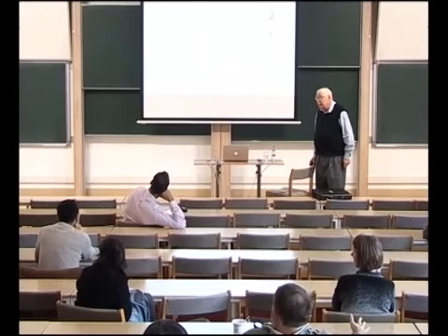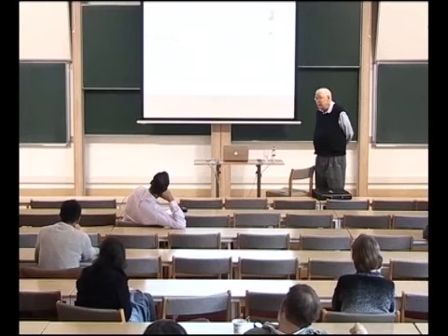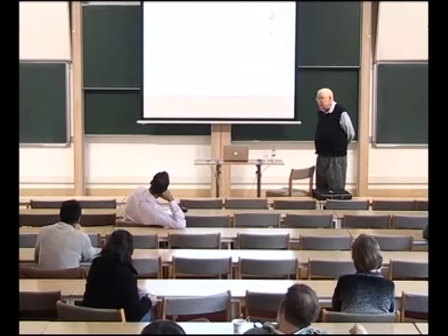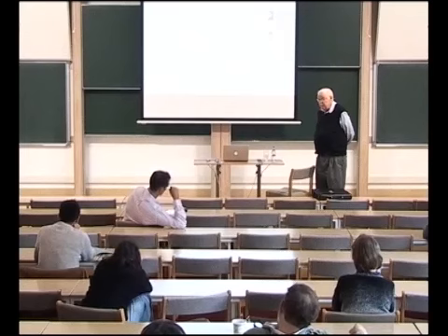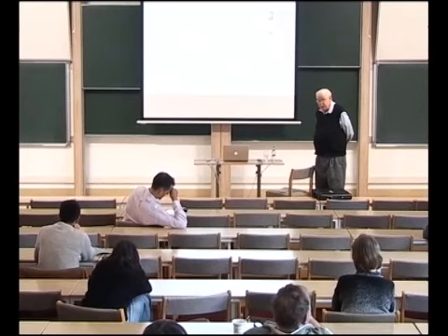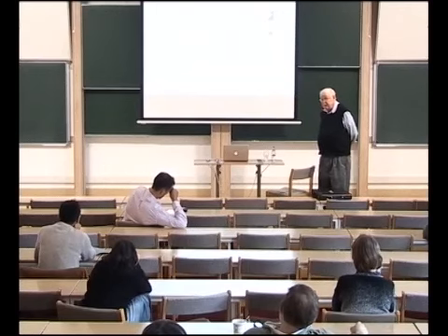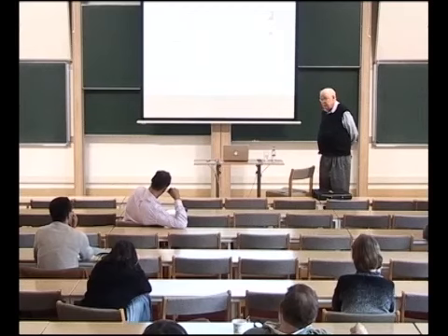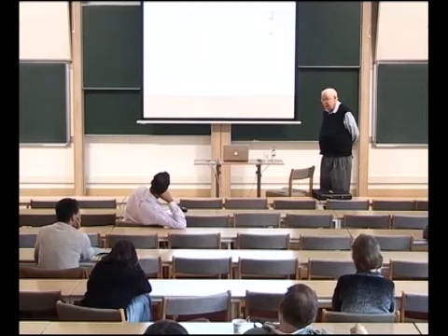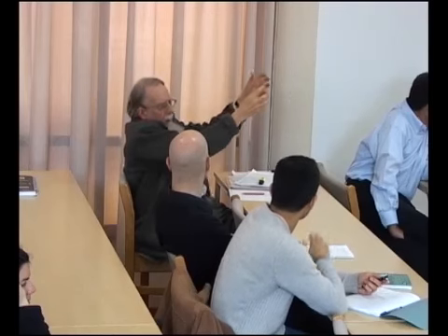Okay, which I take it that means you're using small displacement, so the viscous wake has little chance to develop, because of course those formulae are for inviscid irrotational flow, and in which case the 0.5 and the 1 are perfectly precise. Sure. Yeah, it's got to be small amplitude. There's all sorts of complicated things that occur, even with a simple pendulum at large amplitudes. For instance, I might have a chance at the end of this lecture to just mention some stuff I've been doing about vortex rings from a pendulum.